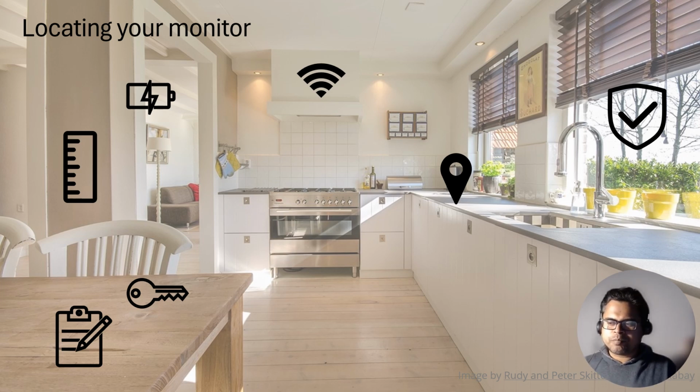Security, as in could people or pets get to it or disturb the measurements. Make sure that you can access the place where you are going to deploy the monitor. Connectivity: if your monitor does not have onboard data logging, then wherever it's located, it should have connectivity, whether by Wi-Fi or cell phone networks, to be able to send the data to the cloud. Depending on if the monitor has a battery or not, you may need to locate it close enough to a power source.